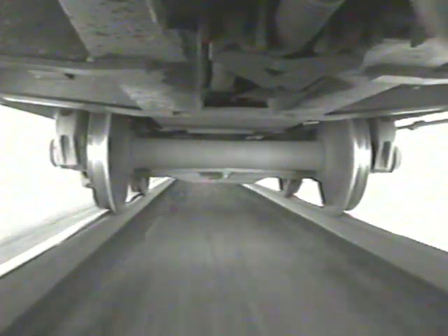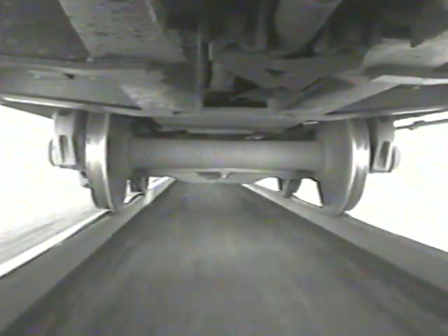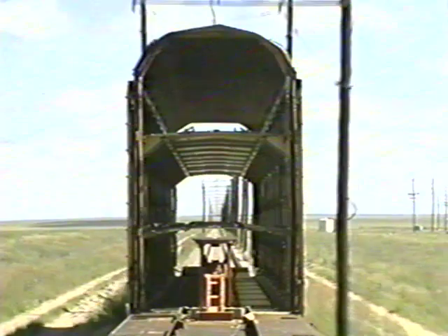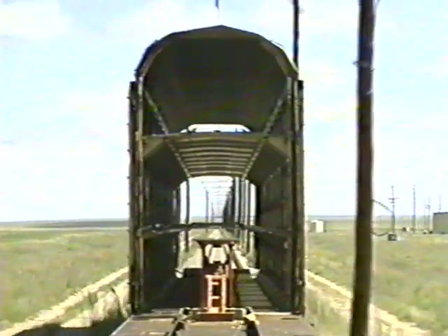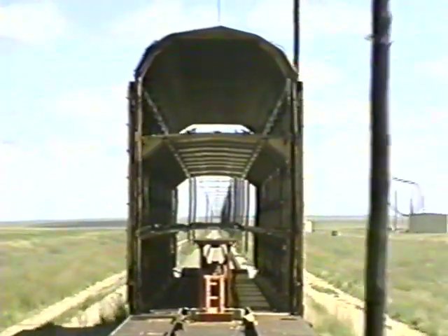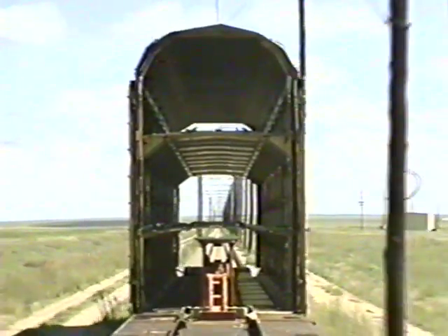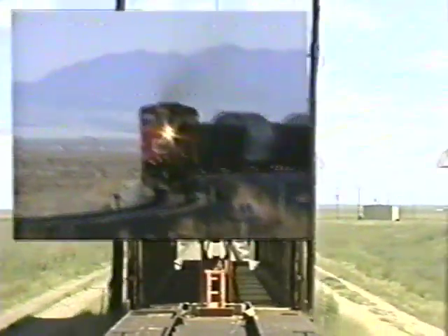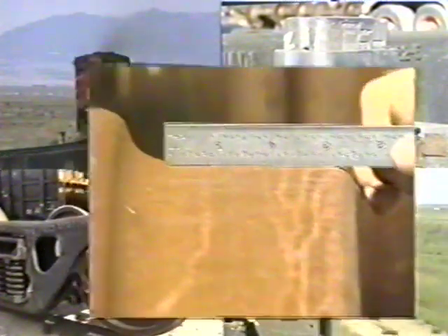The wheels in the trucks move from side to side in a rapid lateral motion. The rapid lateral acceleration of the wheel sets causes them to generate short-duration lateral loads and a rapid transfer of the wheel load from one wheel to the other. If this unstable motion becomes severe enough, the wheel set can climb the rail and derail the car. Hunting instability is affected by several factors, including train speed, side-bearing condition, truck wear, and wheel profile shape.